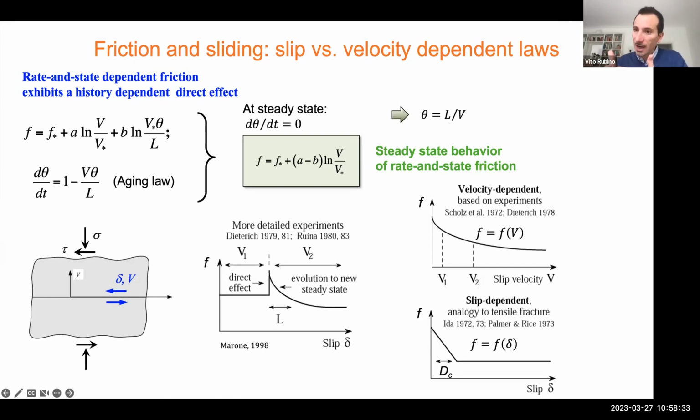But as you move towards the interior of the specimen, you develop plane strain characteristics. So if you have a thicker specimen, you can develop more plane strain conditions, whereas a thinner specimen may tend to reach plane stress, but may not quite make it. In other words, what changes is the interior, but on the outer surface it's basically the same.